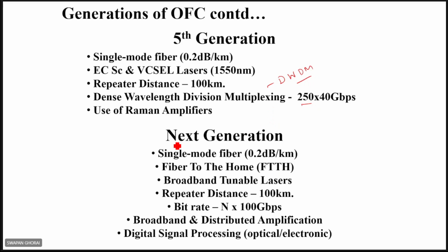And also here, apart from these EDFA and semiconductor amplifiers, Raman amplifiers are also there. In fact, there are different other amplifiers. Probably we'll not discuss them, but to some extent I'll mention them. Raman amplifiers, Brillouin amplifiers. These are based on nonlinear effects. If you go for extremely high speed systems, some nonlinearities will be there, and at that time it is very difficult to amplify the lambdas. At that time, this type of amplifier is called a Raman amplifier. For extremely high speed systems, these are used.